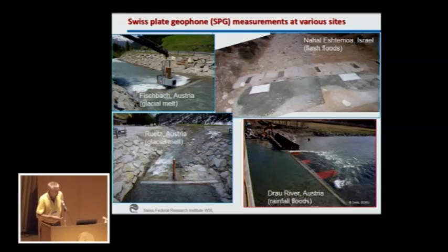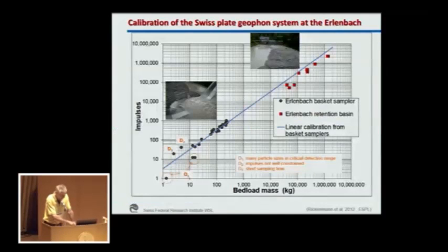Here you have some pictures illustrating some of these sites. Actually, here in these 2 Austrian streams, a kind of upscaled Helley-Smith type sampler is used, here with a metal pillar to guide the exact positioning on the bed just downstream of one of the metal plates.